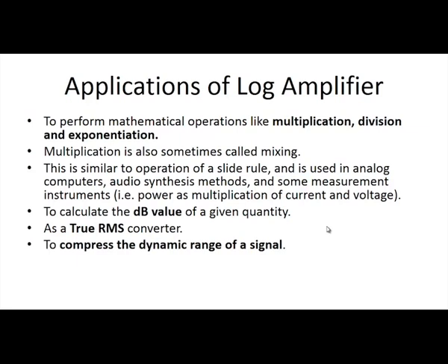So, dB is calculated as 20 log of the normal value. If it is a gain, it is 20 log V naught by Vi, the output voltage divided by the input voltage. So, you have to have a logarithmic value when you calculate the dB value. So, to calculate the dB value of a given quantity, you have to use a logarithmic amplifier.